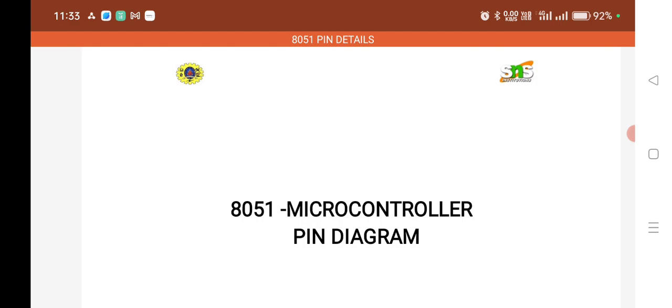And we know that 8086 has 16-bit data and 20-bit address lines. That 20-bit physical address is generated by using segment address plus offset address. Then only we get the proper 20-bit address. So these are the points we discussed in the last class.